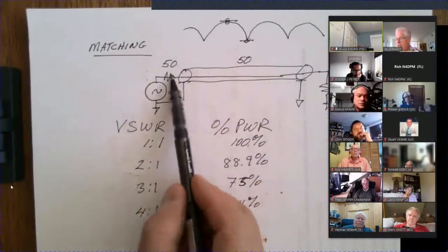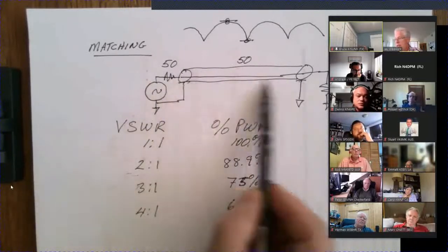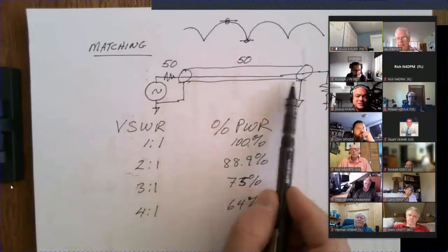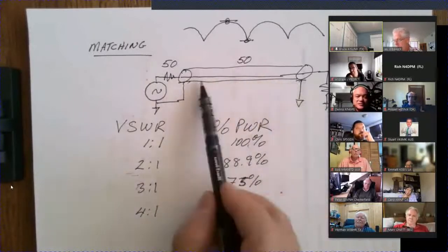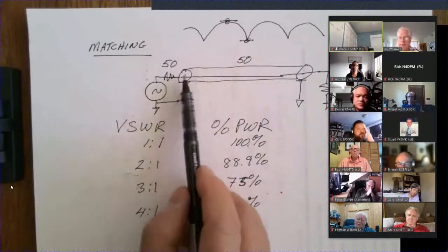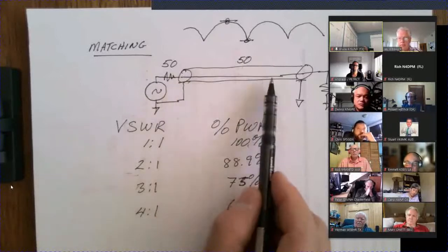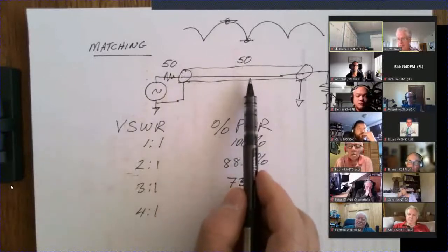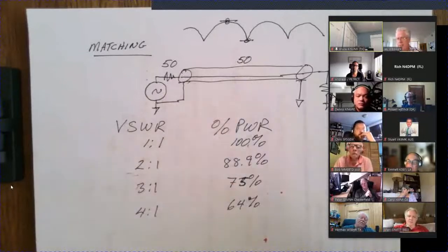If the tuner is here, typically where that power goes ends up heating up your cable, literally. You can get cable losses here, or other effects. There's going to be heating, but that power eventually will go someplace, and it's not usually to radiation. Okay, does that answer your question?